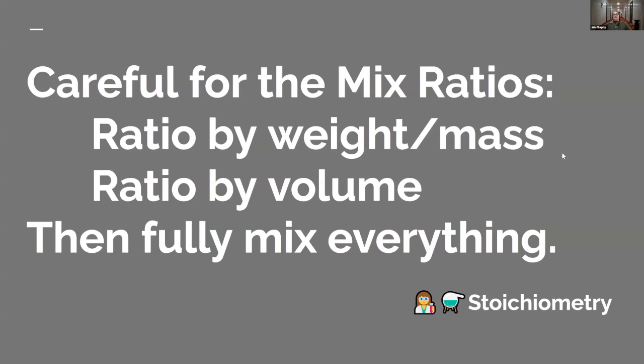The first part of any casting material where you're going to be mixing two things, which is most of them, almost all of them, even plaster, it's plaster and water, you need to know what your mix ratio is to get the right result. It's definitely a cure, where you need a certain quantity of part A and part B to react with each other to make the thing harden permanently. And if it doesn't have the right ratio, it may cure slowly or not at all, or way too fast.